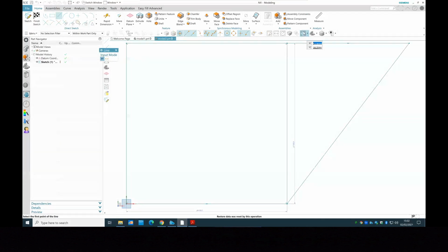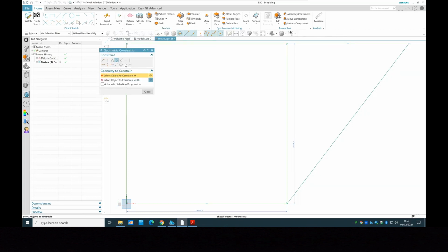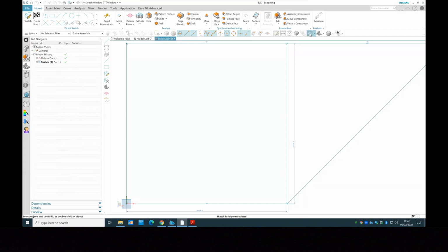So what I've done, I just went to the X and Y plane, and I started sketching a normal rectangle, put the dimension for it, and create these 2 lines. I went to the sketch, X and Y plane, and then made the rectangle, in this case a square because it's 50 by 50, and made these 2 lines. And then once you create those, click on escape, because I don't want to give dimension. I'm gonna go to the geometry constraint and click on the equal length, and I will say the first one, this line, with this one will have the equal length, and you can see the dimension is changing. So already done the full truss.